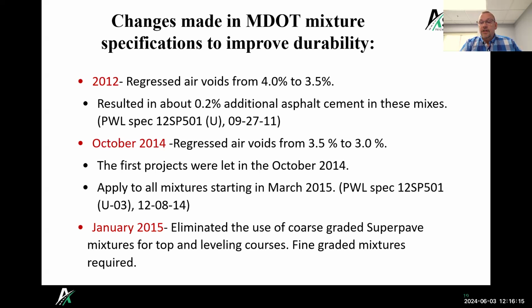And then in January of 2015, we also decided to require fine graded mixes. So when you design a mix, you have your gradation line where you're either coarse graded or fine graded. So we wanted to force all the designs to go to fine graded mixes for all your top and leveling courses. The finer the mixes are, the more liquid asphalt it takes to coat those aggregates. So really that's what we wanted to do, to increase the liquid asphalt content in our mixes and make them more durable. So what exactly is regression?